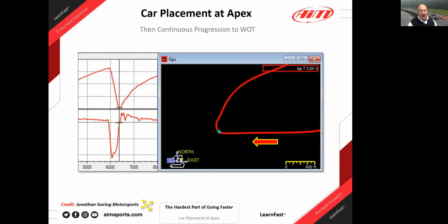I don't know what the spike is just before. Could be a bump. I know that this section of the track is pretty bumpy. I don't know if he lost traction or gained traction, he might get a little bit more longitudinal G positive, which is above this black horizontal line. But for now, we're just going to smooth this out and say, look, we've got lots of fast, quick attack and good brake aggression. We have a peak early in the brake zone. Then we see a nice trail off.